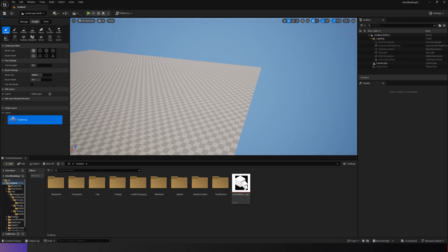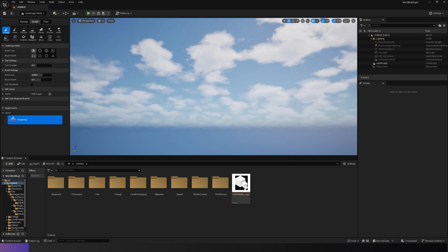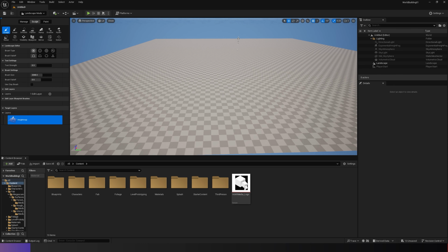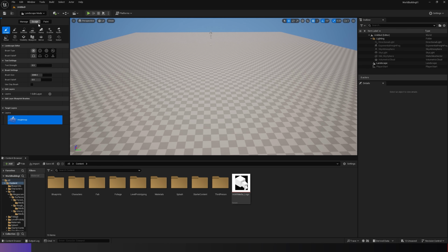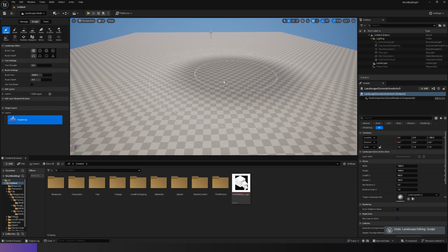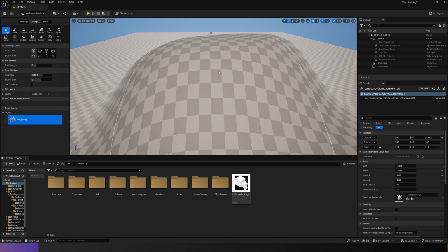And this will create us this UV mapped surface here. If I was to look underneath it, you can see it's transparent. So this is essentially a plane. But once I have created our landscape, we'll notice it automatically goes to the sculpt mode. So our sculpt tool, try to think of this like we're working with clay. We can sculpt by adding, or we can sculpt by taking away. If you want to take away, we'd hold Shift and click, and that would carve into our landscape. And if I was to just left mouse click and drag, that would add to our landscape.